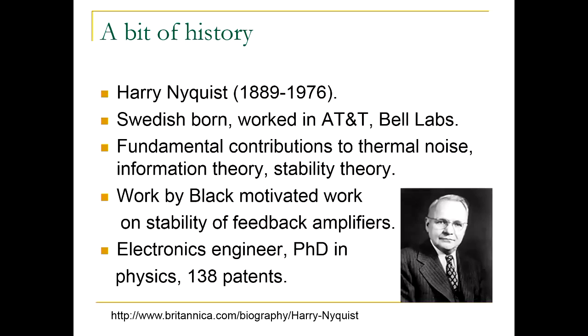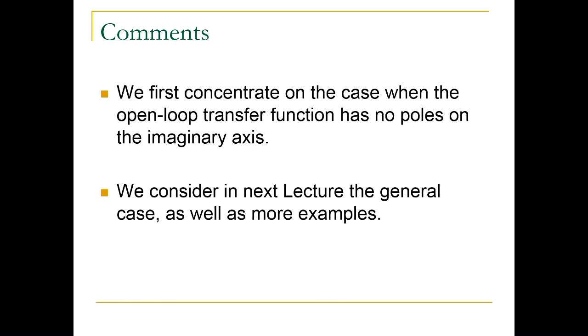This guy really did heaps of useful work in control theory. Some of these things are listed there. For us, we will mainly use his work on stability, which is Nyquist's stability criterion. All right. What we will first concentrate on is the case when the open loop transfer function has no poles on the imaginary axis. And then in the next lecture this afternoon, we'll consider the general case where we allow some poles to be on the imaginary axis. Okay?